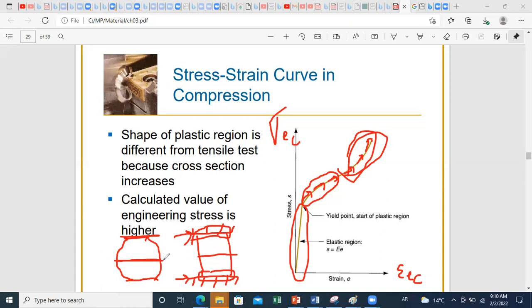And for a considerably large value of epsilon, this will lead to certain deformation. So this is why in case of compression, we say that one of the failure modes is that we reach a very important deformation state, and we consider that a certain stage of barreling can be defined as the limit of the compression test. Okay. Now in compression, we have several modes of failure.